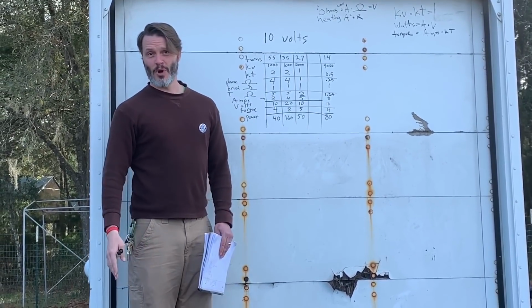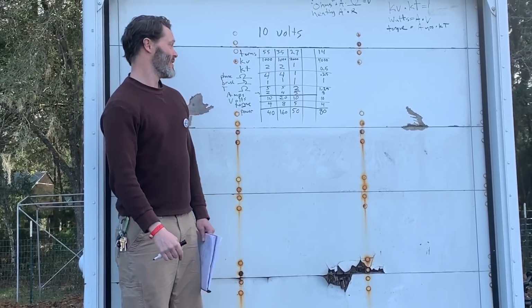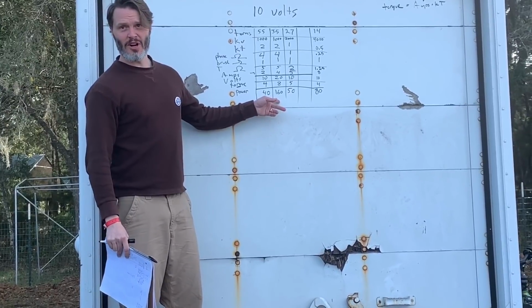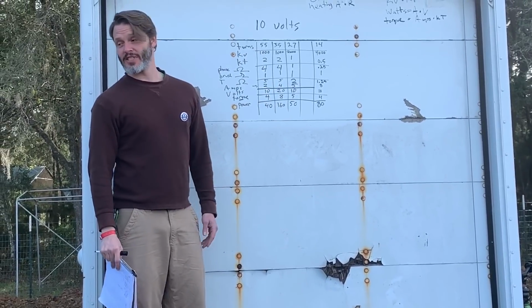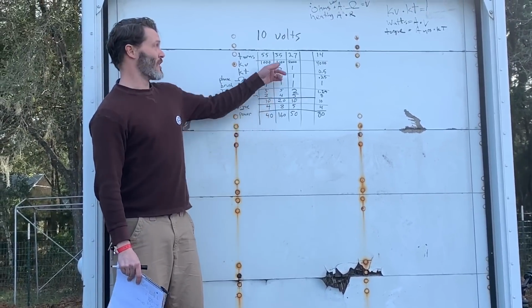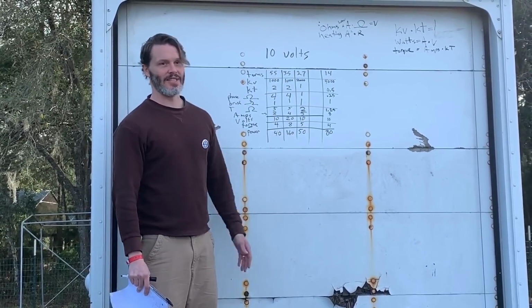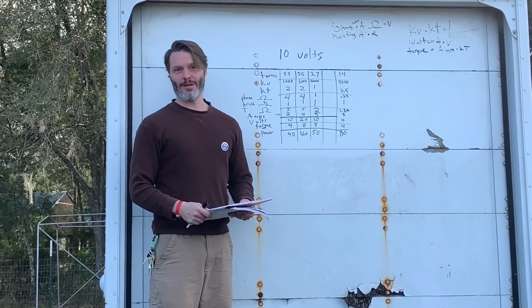So you doubled both your torque and you doubled your wheel speed. Looking at it, it's looking like this 55 turn motor running on twice the voltage is actually going to give us a lot more torque. Of course, we could do the same to the 27 turn. We run it on 20 volts, and it's going to do the same thing. It's going to double torque. It's going to go 4 times the power.